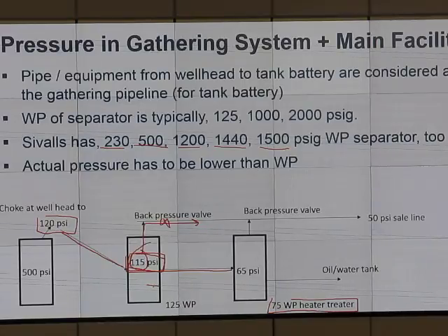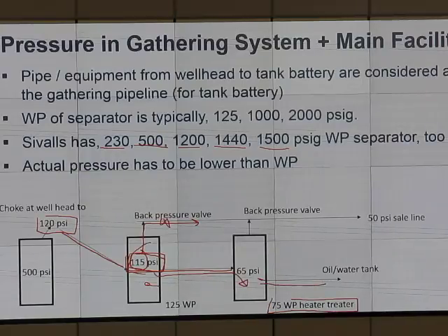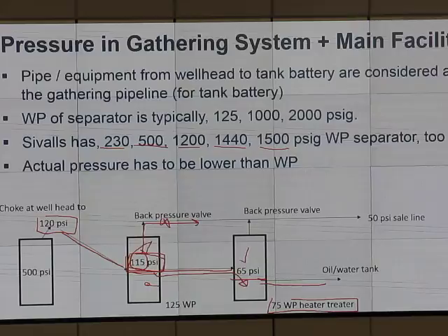So the dump valve opens, right? You have the float and the dump valve opens. Whenever the dump valve opens, liquid goes to this tank. When liquid goes to this tank, if the liquid level is too much, this dump valve will also open and it will go. So that one closes and then this one will close. So you have enough pressure. You don't use any electricity, you see. You have enough pressure to push from one tank to another tank.